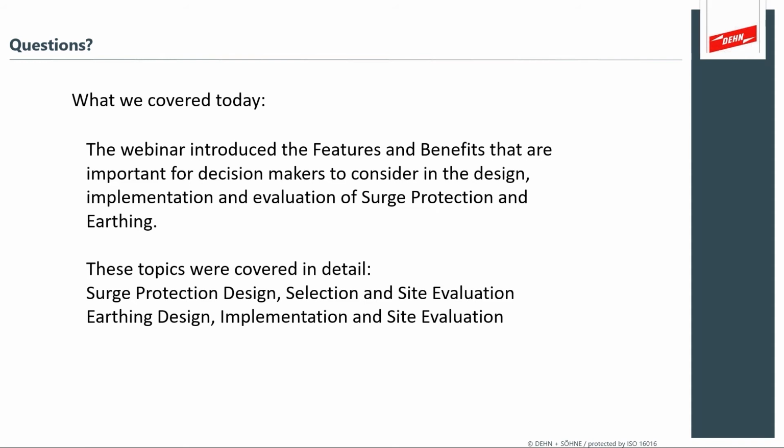Yes, Mark, I would just like to add that you select a certain lightning protection level in your risk assessment, and that guides you to what SPD you need to select. And you'll notice when you do the risk assessment that if you select a more stringent lightning protection level, say a lightning protection level 3, 2, or 1, that's higher than a lightning protection level 4, the risk keeps on reducing even though you've just implemented the same surge protection measure.